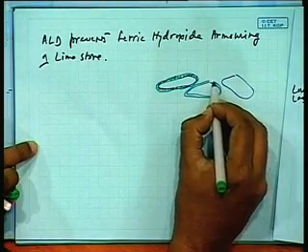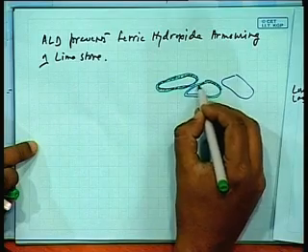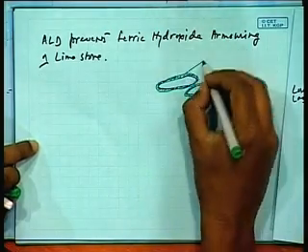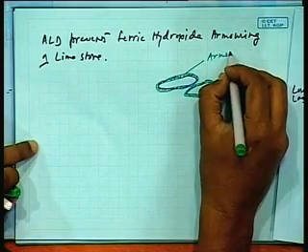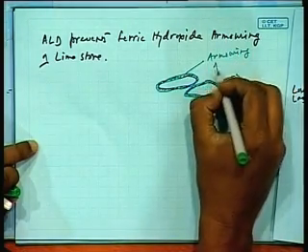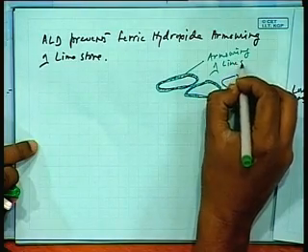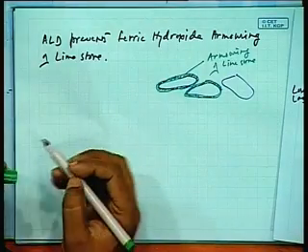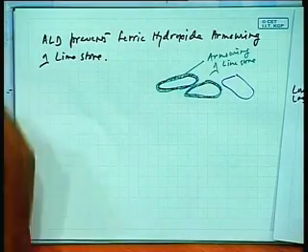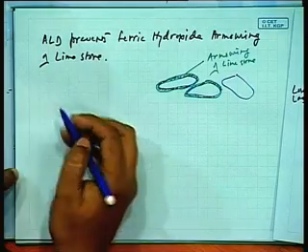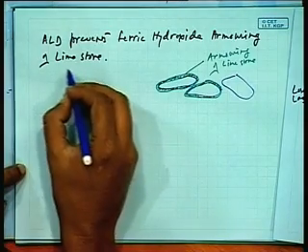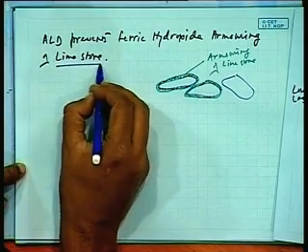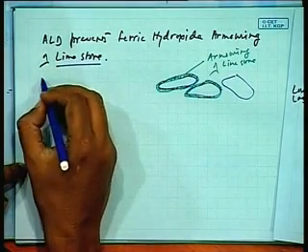So we would stop the ferric hydroxide deposition here and reduce the ferric hydroxide. This is called armoring of limestone, where the limestone chips get coated. The ALD prevents ferric hydroxide armoring of limestone.